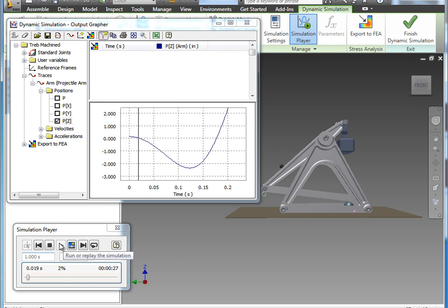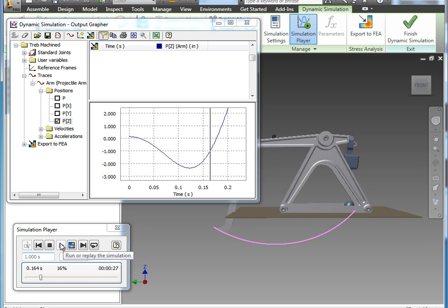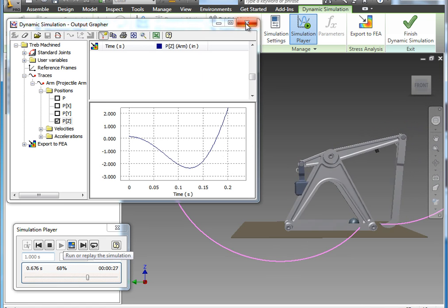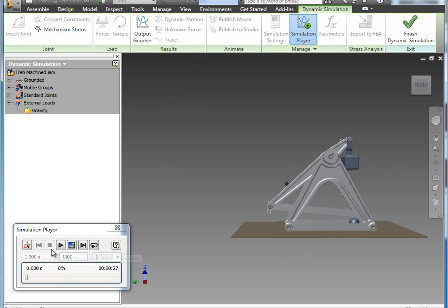So this is providing you information in a graphical and visual format in the scene as to what's happening in the simulation. I wanted to call out this specific point because with the first joint, we're going to fix this. And it will change the graph and the tracer. So I'm going to go ahead and close the graph for now. And let's jump back to construction mode, and we can go ahead and make our first joint to work on making the arm drag along the floor.